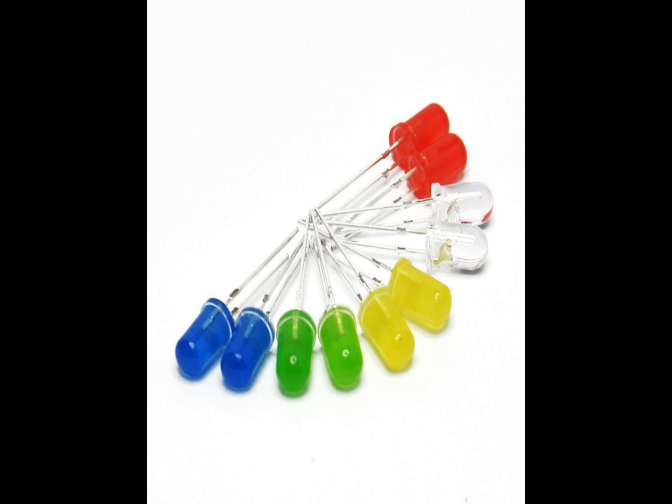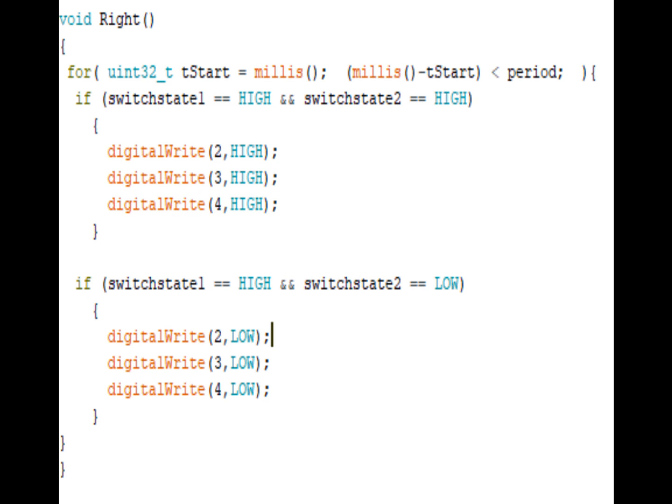Moving on, the void loop includes digitalWrite and delay as the main functions. digitalWrite is another important function which we must consider. The digitalWrite function is used to set the value of a pin as high or low. When we choose the high option, it sets the voltage to either 5 volts or 3.3 volts, depending on the microcontroller. For low, it sets the voltage to 0, which is the ground state. If we do not set the pin mode as output, the LED will light dimly.